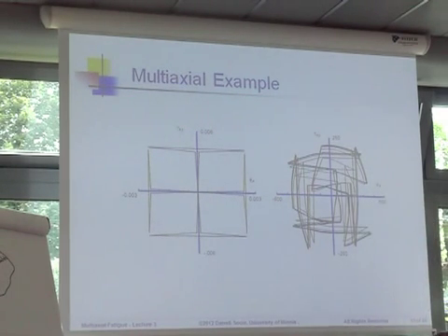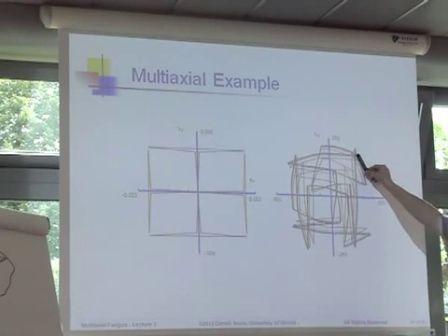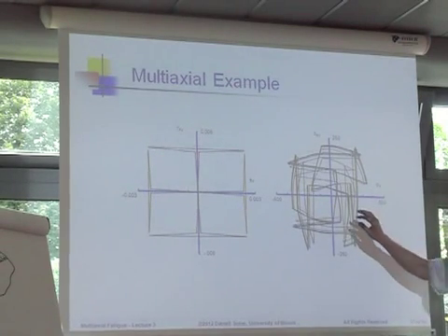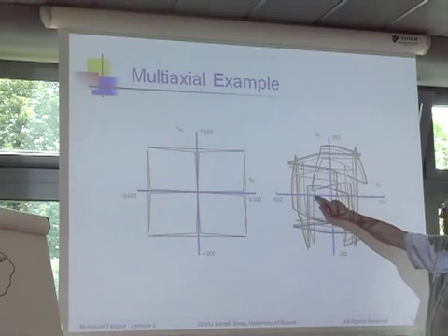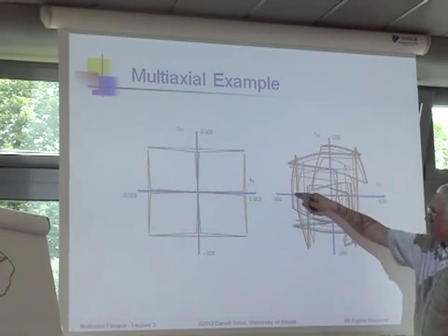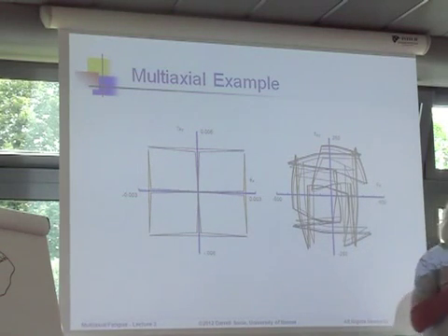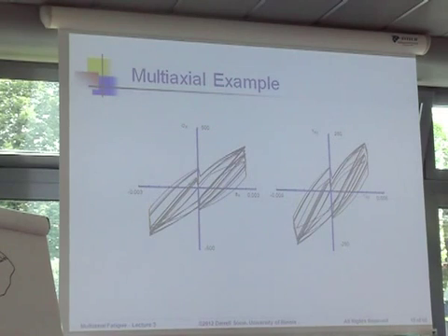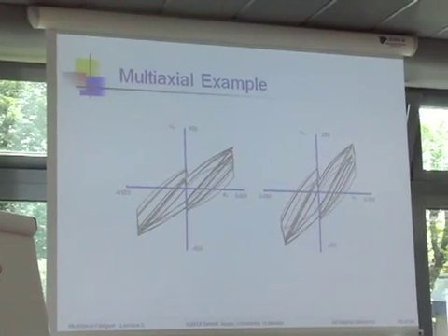You can see certain features in here. Of course, you can see the features that I pulled this in tension, and so I have a mean stress here, and I twisted it here like that. And you can also see other features, like here's the interaction of the tension and torsion loads in it. And the other thing you can see is that with time, you can see this thing actually growing, right? This was the initial cycle, and later it's just grown and become bigger and bigger, so that's all that sphere getting bigger. So they work. I consume too many hours doing this kind of stuff. And there's what the individual stresses look like if I were to plot the stresses in the XY system.